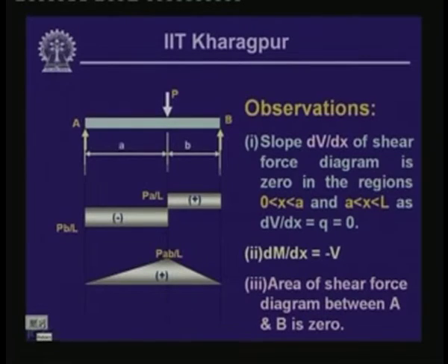Well, now that in the last lesson we had discussed the features of shear force and bending moment diagrams, how to plot them, and we had defined what shear force and bending moment diagrams are. Now, based on the examples which we had seen last time, both a simply supported beam subjected to a concentrated load and a simply supported beam subjected to uniformly distributed load, let us look into some of the salient features of shear force and bending moment diagrams.